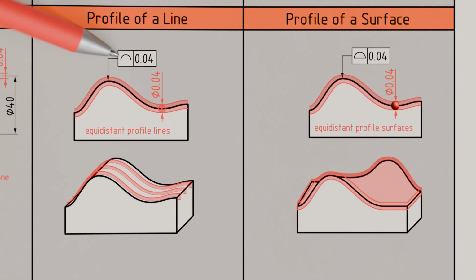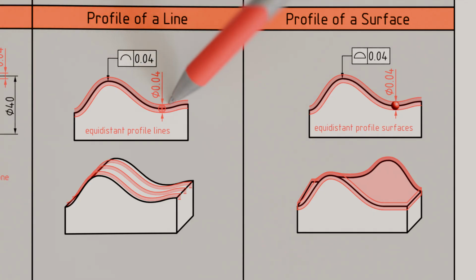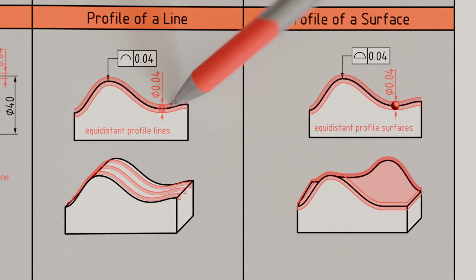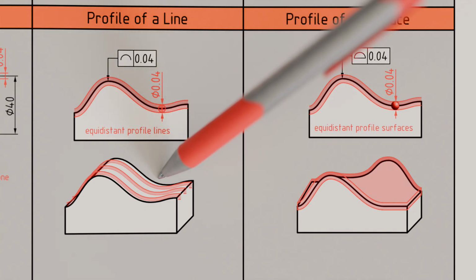The line profile tolerance is a generalization of straightness and roundness. The arbitrarily curved profile line must lie between the envelope lines of infinitely many circles whose diameters correspond to the form tolerance value, and whose centers lie exactly on the ideal geometric profile line. In each parallel cross-section, this profile shape must be independently maintained.